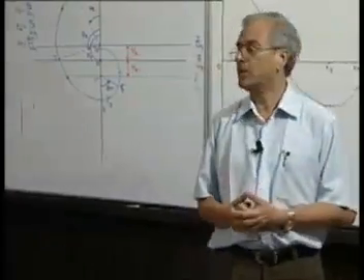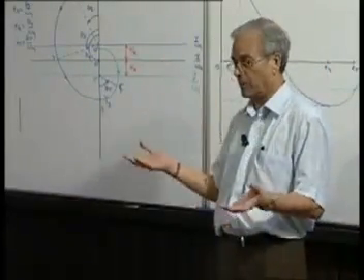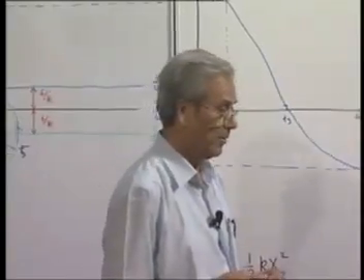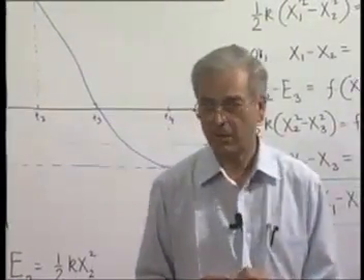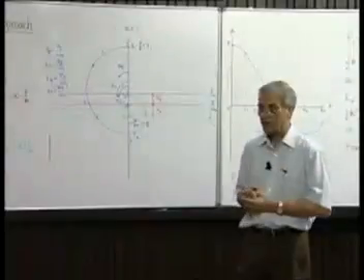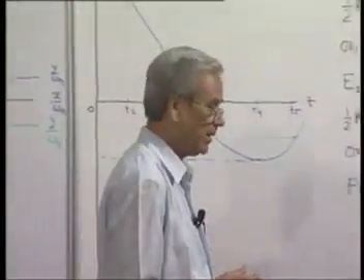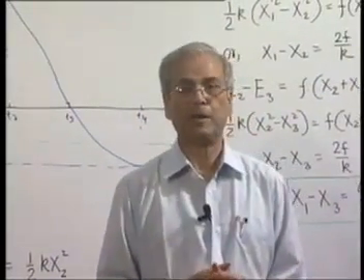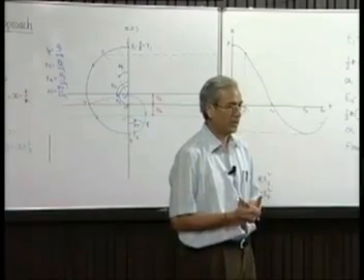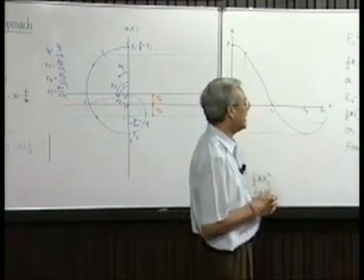And in case of Coulomb damping, you have seen that the natural frequency or the time period remains the same as the undamped system. We have further seen that in viscously damped system, the amount of damping determines the nature of response to its initial disturbance. We have seen that for each particular type of system there exists a value of the damping coefficient which is critical. If the damping coefficient of the system is above that, then the response is aperiodic, but if it is less than the critical value, then the system is periodic, though with decreasing amplitude with time. In the next lecture, we will start the determination of the response of a system to outside oscillating disturbance or force. That means we will start our discussion on forced vibration.